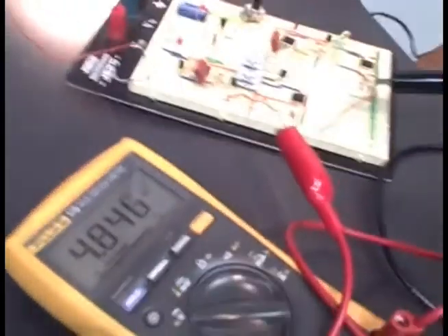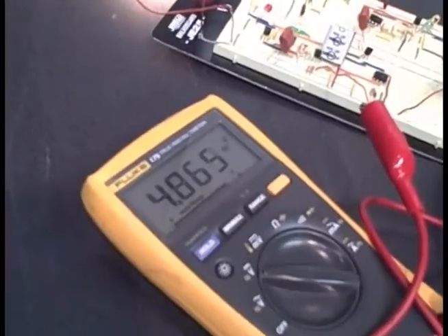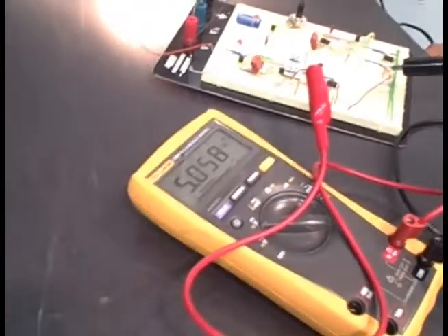All right, so as you can see, this LED is still flashing, and now that it's reaching 4 volts, it should start switching. And the green is flashing now, which means that it's over 4 volts, and our circuit's still working correctly. And it's at about 4.3 volts, and so in about 0.7 volts, this capacitor should stop charging. No, wait, not yet. Why did it stop?